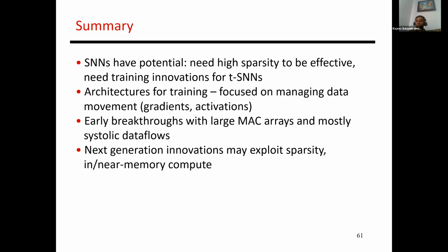And again, if you're doing it in analog, even a spiking neural network has weights, right? And those weights are what you would put into each of those resistive elements. It's just that the inputs are now spikes, which makes life a little bit easier. Even the outputs are spikes, which means that the ADC is just a 1-bit ADC, right? You're just deciding 0 versus 1. And I think in the Nebula paper, they talk about different ways of implementing the sense amplifier. So that's a good place to look at for an analog design of a spiking neural network.